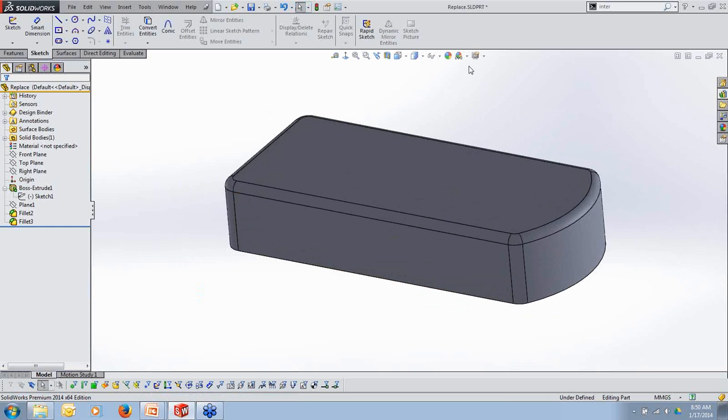When you're working in SolidWorks, you've got your model that's shaded. And there's various modes of shading in SolidWorks, right? We've got our RealView graphics that we can turn on. We've got shadows that we can add, and ambient occlusion, which shades based on the surrounding geometry. Then we've got perspective, which isn't part of shaded mode, but it's in the same vein, so they include that there. If we ratchet through these, we can see that our graphics change. None of these are actual rendered images.